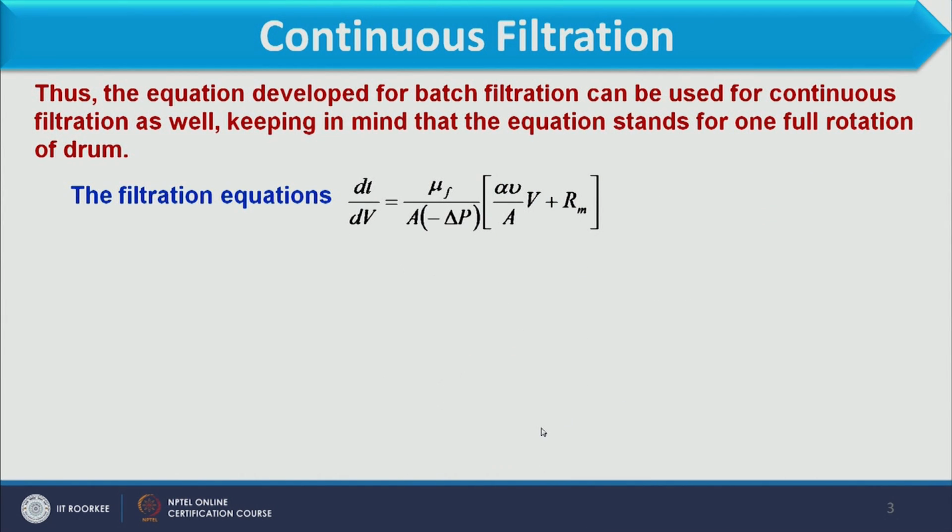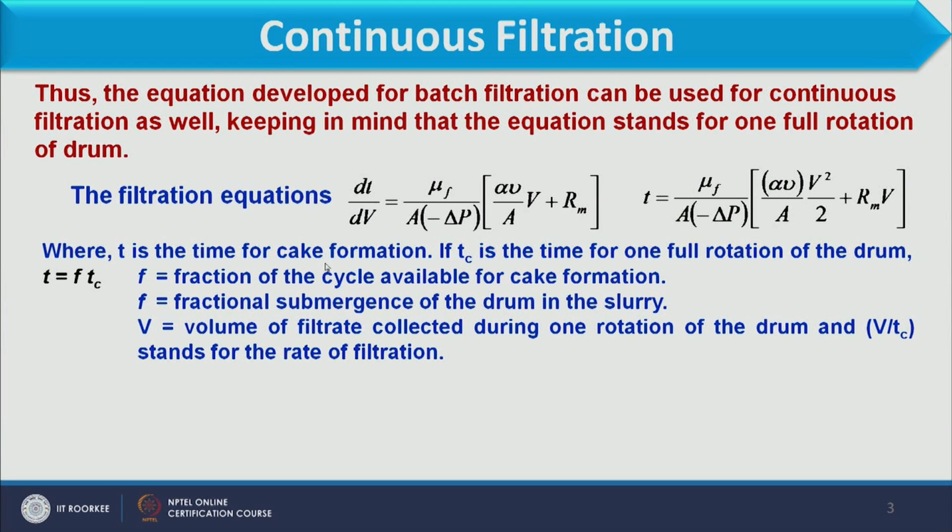So the final filtration equation, if you remember, we derived in lecture 2 of week 2. When we integrate this, we can get the time expression in terms of volume, where t is the time of cake formation, and V is the volume collected. V is the volume of filtrate, so in whatever time the filtrate is collected, in the same time the cake formation is carried out.